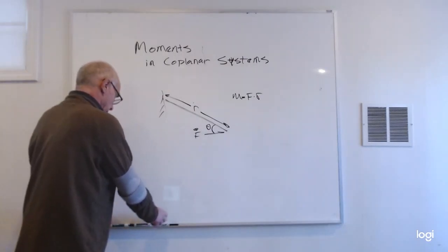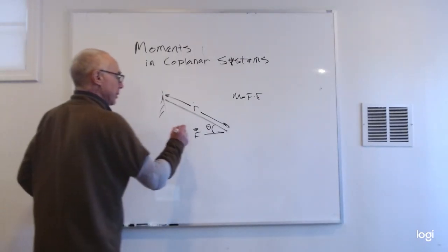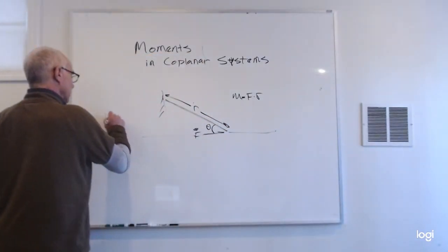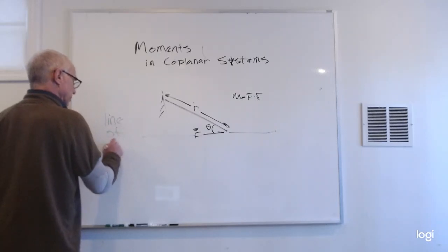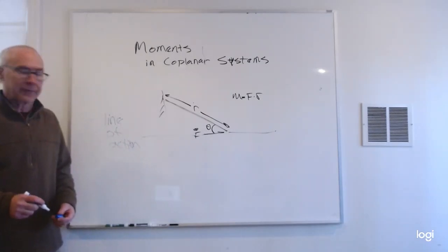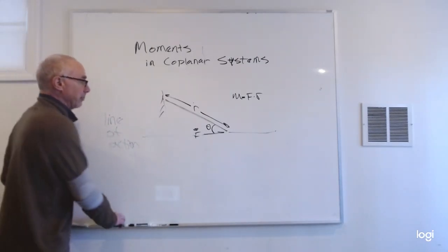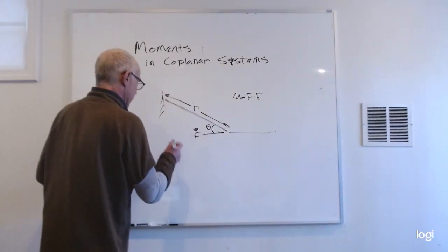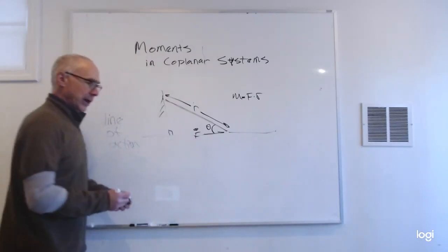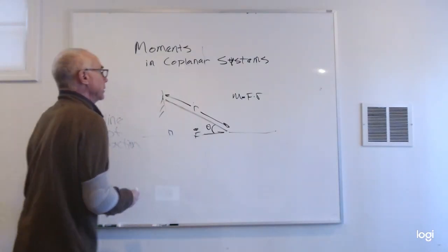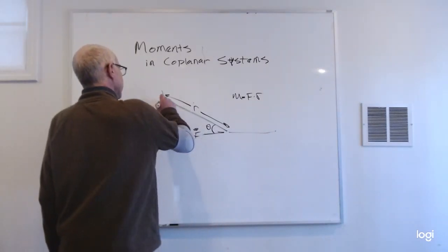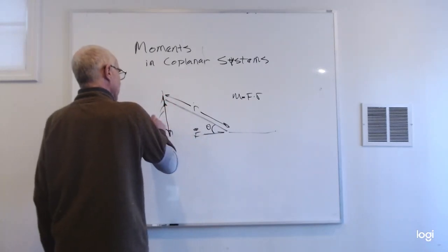Now I'm going to draw my line of action, which seems to be always in blue. That's my line of action. So that's where we're drawing our force. And now we find the perpendicular distance, which will be essentially from here straight down. I'll draw my little green box to show that it's perpendicular. Now I'm going to draw my line connecting these, and this has a length of, we're going to call that D,